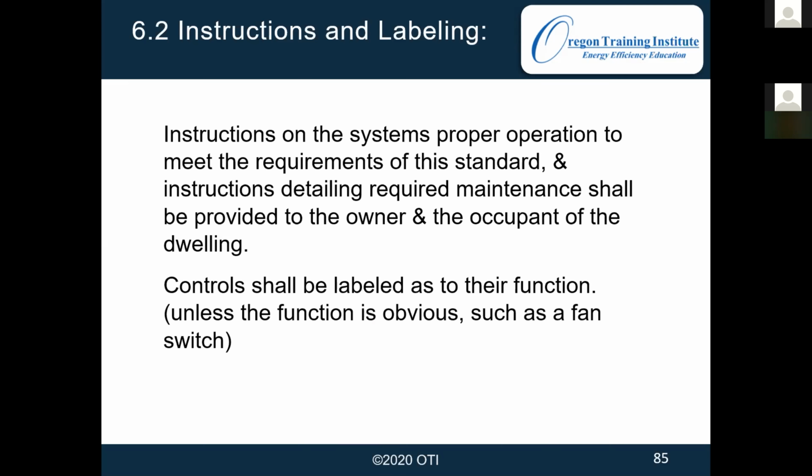So the switch has to be labeled, or if it runs without a switch, then the fan needs to be labeled on how to turn it off, which could be inside the fan. So you could say controls behind the fan, or if there's not any controls behind the fan, then at the breaker box.